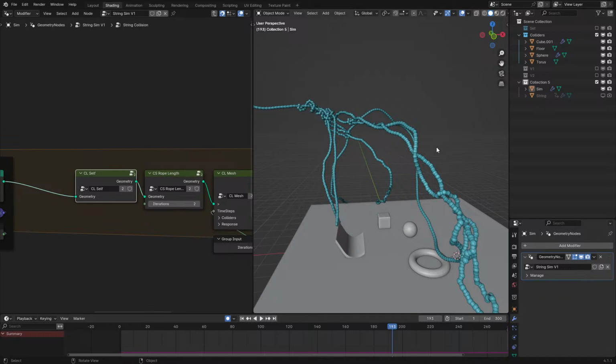Because if I wanted to do this rope sim in Houdini, it would be, okay, I need to take my environment, export it as an Alembic or a GLB, depending if it's moving or not, import it into Houdini, set up the sim with the objects that you need, export the sim as an Alembic or something else, import it into Blender, make sure you have the cache and all that, and it all works.